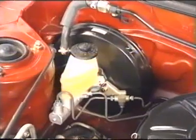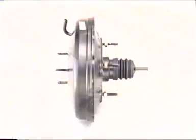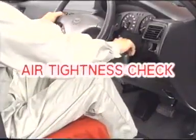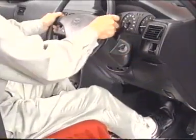If there is a problem with the brake booster, it could cause unexpectedly strong or inefficient braking. There are several, although not perfect, ways to inspect the brake booster. First, check air tightness.